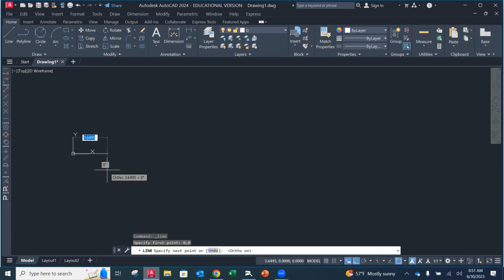And as I look at this, that's all I want to do right now for the lines that I'm putting in place. So I'm going to go straight down. We started up in that upper left-hand corner. I'm just going to push my cursor down. I haven't clicked. And now I'm going to use this dynamic input. Does everybody have that input where I can key in a number right now? It's showing me how far I've actually pushed my cursor.